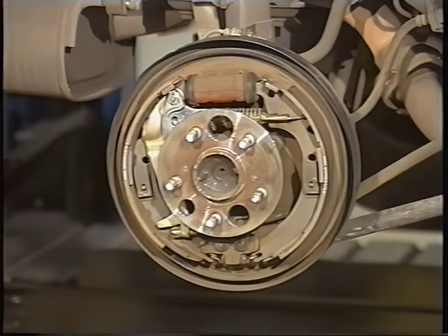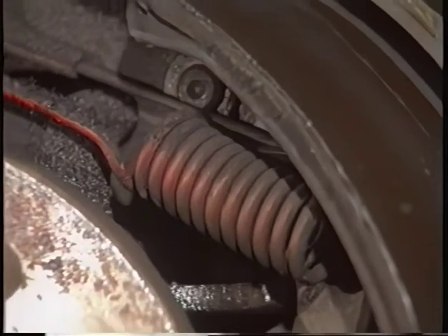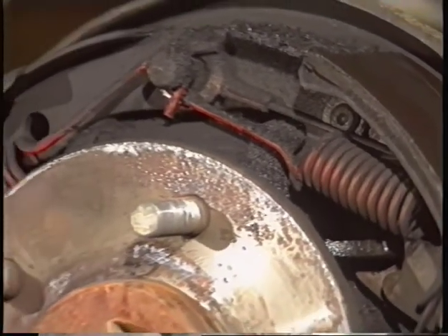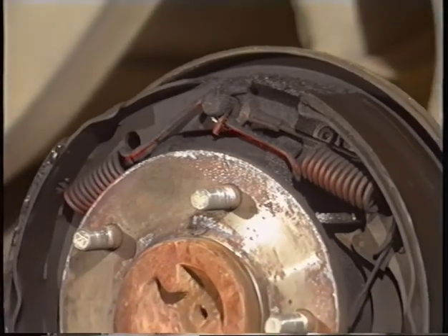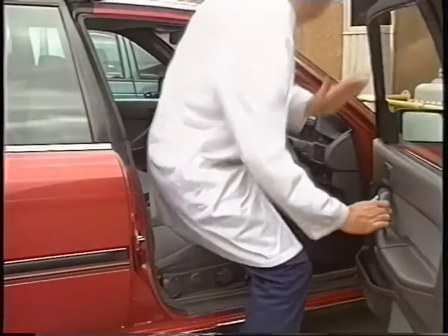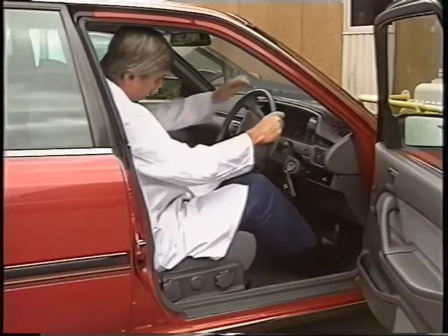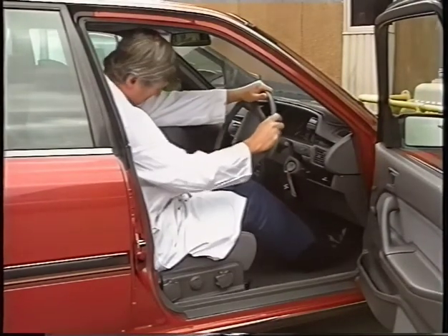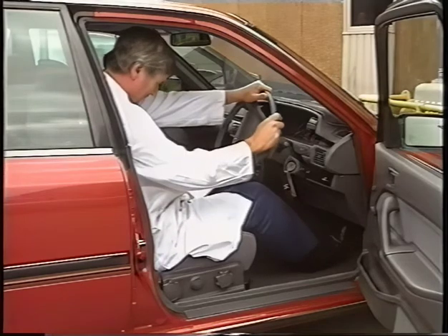Mechanical problems are usually attributed to excessive clearances in service brakes or pedal and booster assemblies. Hydraulic problems, on the other hand, are usually caused by circuit failures due to fluid leakage or internal faults in the master cylinder. If there is doubt that a problem exists, a comparison can be made with the brake pedal height of a known good vehicle of the same make, model and specification.